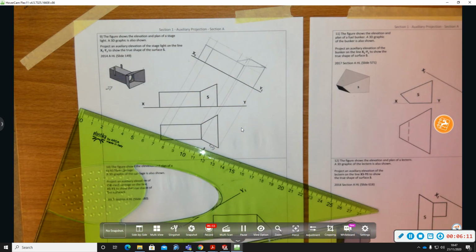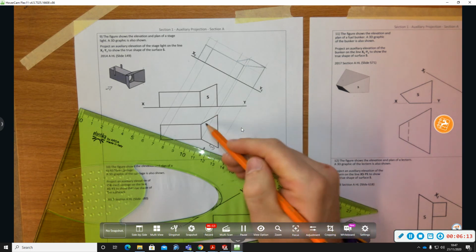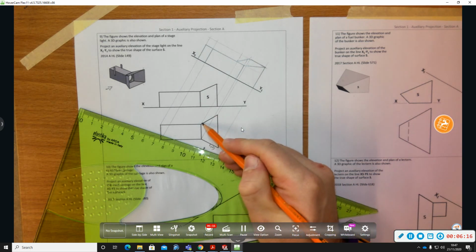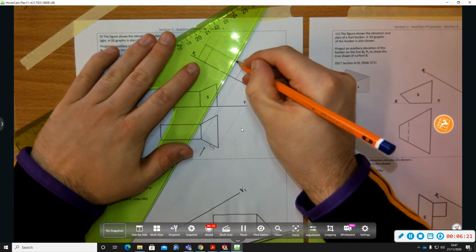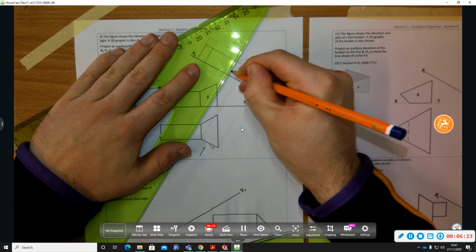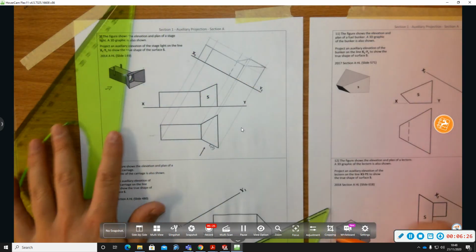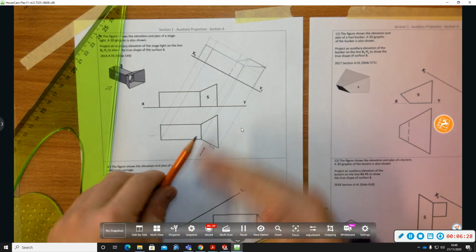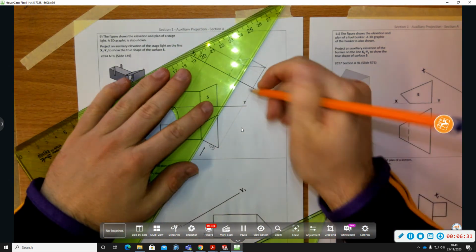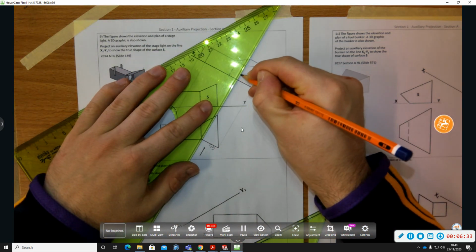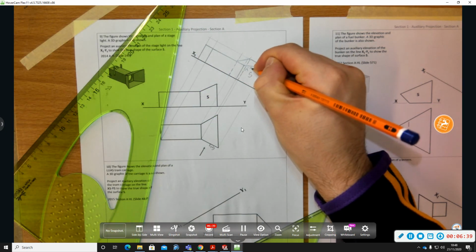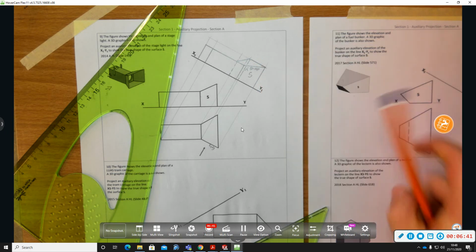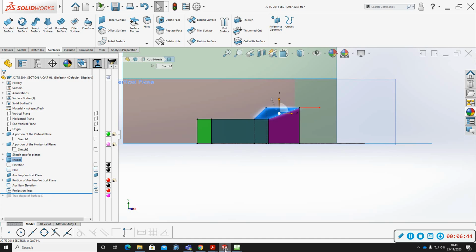Now, where's my heavy and hidden detail? Well, two surfaces intersected at a line, so this is going to be hidden detail. That line at the back is going to be hidden detail. And then this line here I can't see, it's blocked, so that has to be hidden detail. And there's the true shape of surface S, as we can see. There you go.